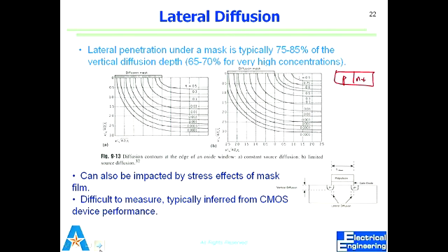This was N type and this is P type. It is a region where there are not many majority carriers. There will be some extending to this side also, but this side is way higher, so we ignore that. We say most of the depletion region is towards the P side.